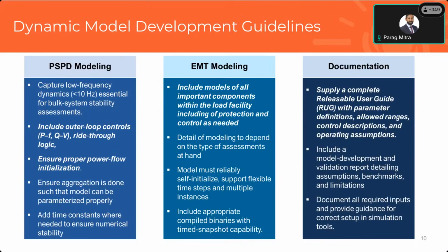We need to make sure that the aggregation is done properly because these models won't have a lot of details. There's going to be a lot of aggregation. And when we're doing aggregation, we need to provide guidance on how parameters of an actual facility can be tuned or modified to fit this more aggregate model. And then, like I spoke about in the last slide, numerical stability is important. There are certain coding practices that lead to these models being more numerically stable, including adding time constants when needed.